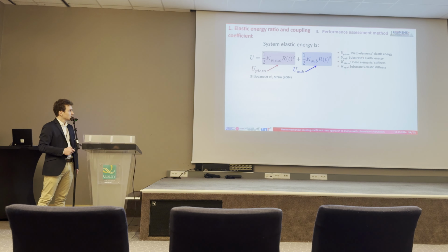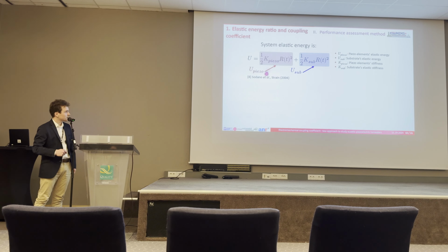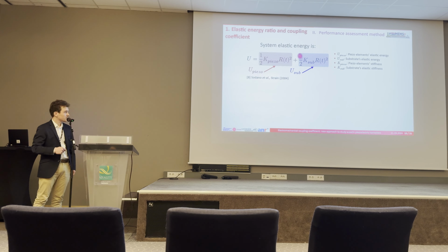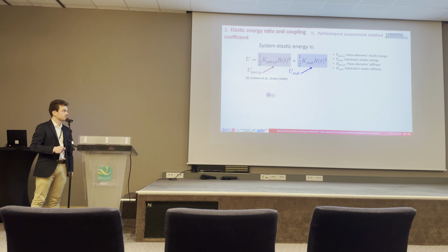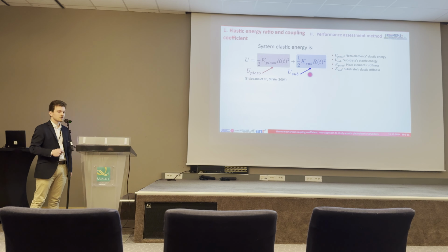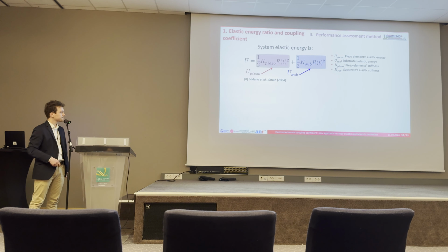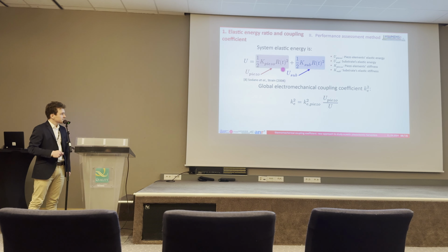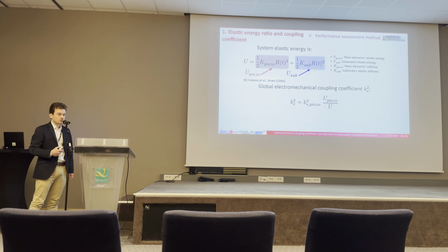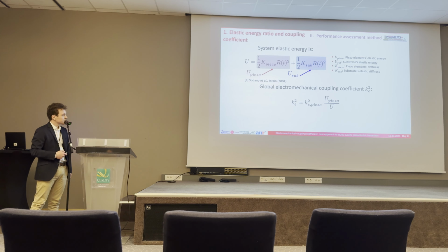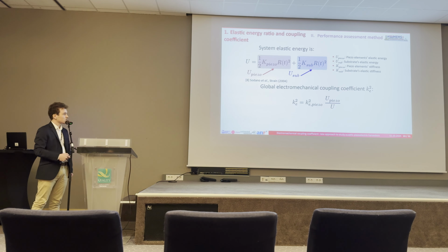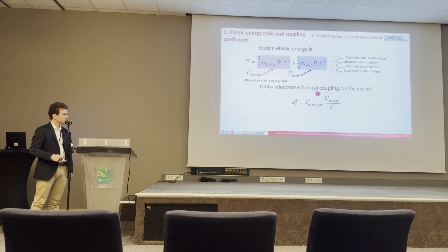So here I give the elastic energy to introduce the subject, which is the sum of the elastic energy in the piezo element plus the elastic energy in the substrate. We can see here the global electromechanical coupling coefficient, and as I said earlier, it's proportional to the material coupling coefficient linked by the energy ratio.